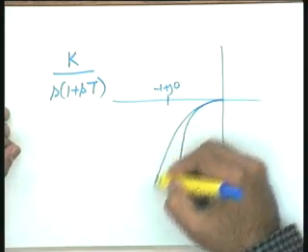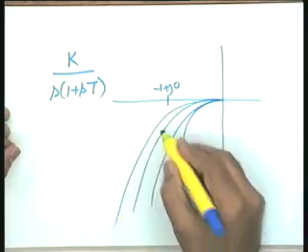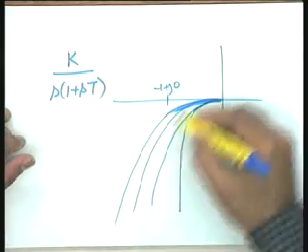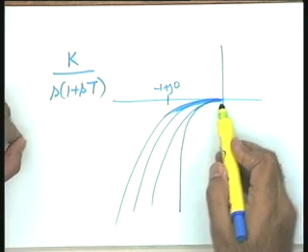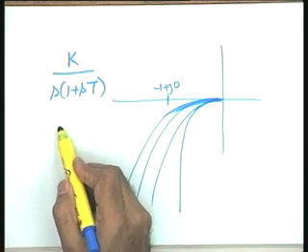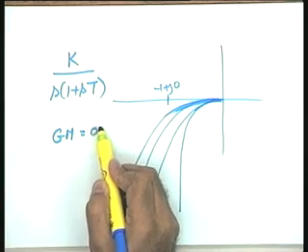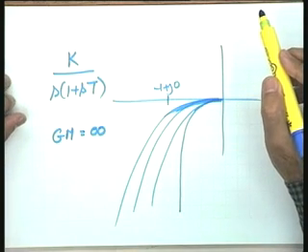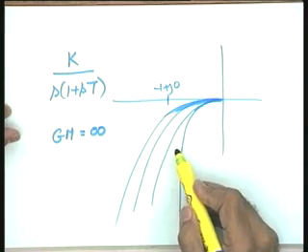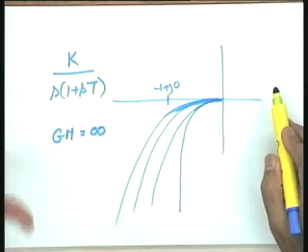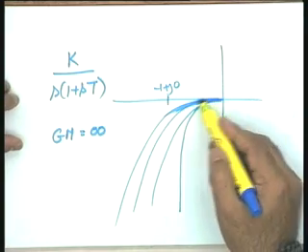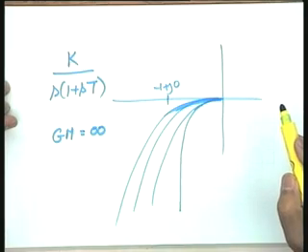Now, you increase the value of k, any amount you increase the value of k, it has to become asymptotic to this particular line, and since for every value of k the plot is asymptotic to this particular line, in that particular case you can say that the plot will never intersect, and hence the gain margin in this particular case is infinity. But you have not to be very happy that the gain margin is infinity. It simply says that for such systems where the intersection is not there, phase margin is the prime index of relative stability of a system, because it tells you how close it goes to minus 1 plus j0 point.